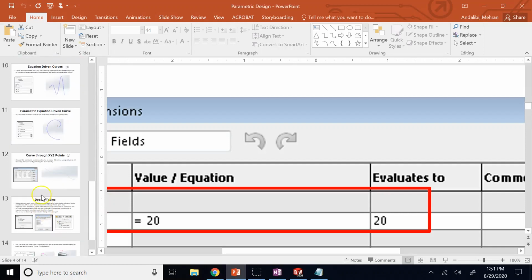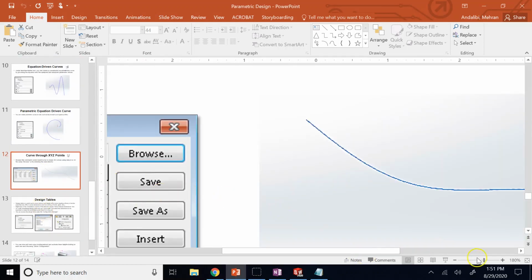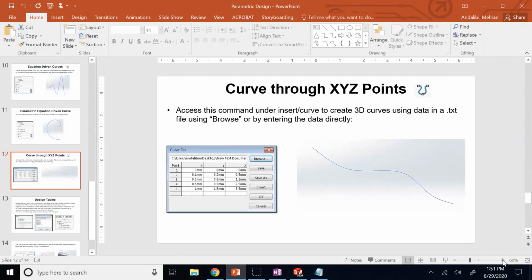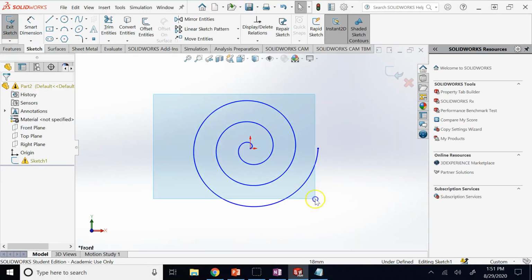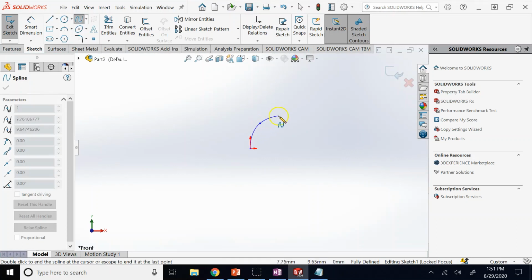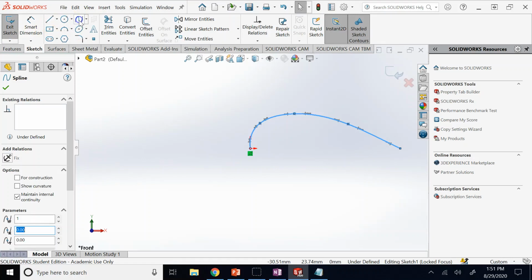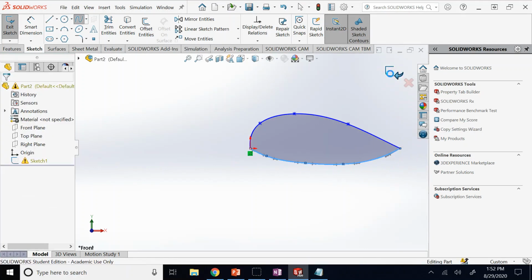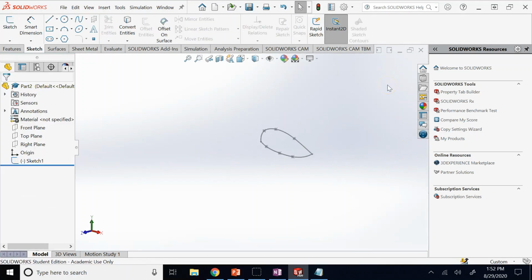Anyways, one more thing that I want to show you is a 3D spline. So far, the spline that you have seen, and it's useful for creating so many objects, is a 2D spline. So you have to do it basically by going to a sketch plane and then clicking on a bunch of points and basically making your spline pass through the control points, right? So this is a 2D spline. It is in a sketch plane, on a flat plane.